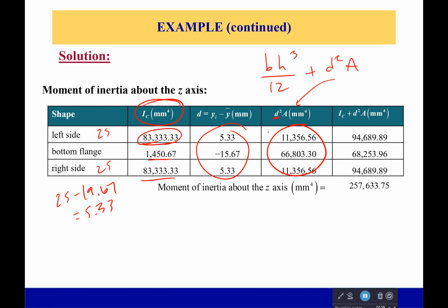So we calculate this correction term, and then we add them all together to see what our total moment of inertia is, and it's right here. So we add all of the moment of inertia about their own axis. Then we add these correction terms, the parallel axis theorem, and when we've done that, we get our total moment of inertia. Okay. So we have the centroid now, we have the moment of inertia. This is going to be a very common thing. You're going to see it every single time. So get used to making these tables. This table is probably the best method to do it because it's just a good way of note keeping. You never forget what you were supposed to write down.